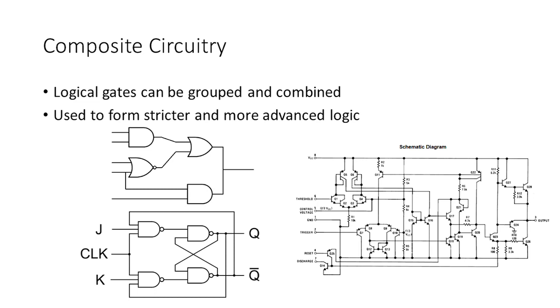constitute the output. Below that circuit on the bottom left, we have the circuitry for a basic logical flip-flop. Also referred to as a latch, these circuits are capable of storing the value, either high or low, for a certain amount of time. If you ever heard of the term volatile memory, this is what volatile memory looks like at the schematic level. When the circuit loses power, the information stored in this flip-flop or latch is lost, and it's not persistent. But it can store a bit, either a 1 or a 0, so that programs running in a microprocessor or a more complicated logical circuit can pull information and store information to a register or a series of flip-flops during the execution of the program.